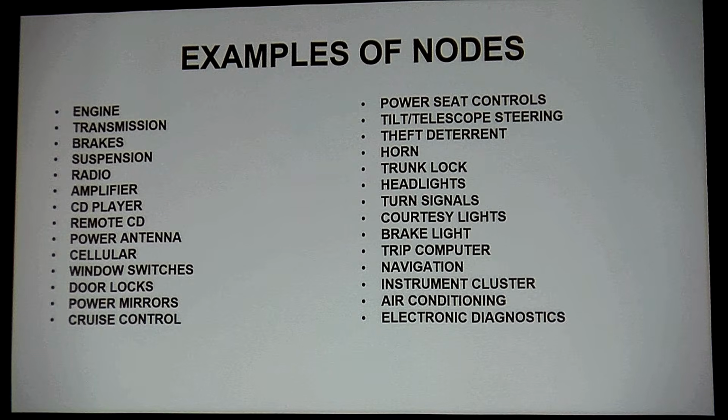Speed is money. The faster the bus goes, the more money it costs the manufacturer. So the manufacturer is not looking to spend any money that they don't have to spend. So I can split the bus systems up on the appropriate system, so I'm only going to have these high-dollar transceivers that go really fast in the modules that need them, in an engine control, in an ABS. Why would I have a really high-dollar transceiver to open a trunk or to put my wipers on?